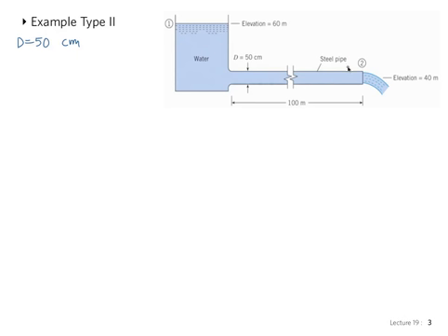And so for commercial steel, you can go inside a handbook or some spec sheets or a table or whatever, and you can get for commercial steel the value of the roughness. We get epsilon, the roughness, equal to 0.046 millimeters.